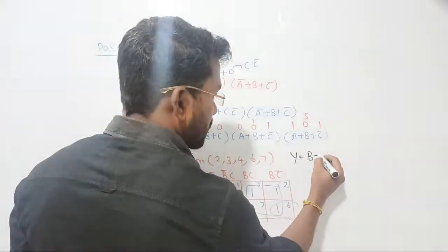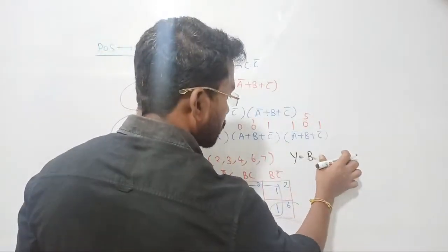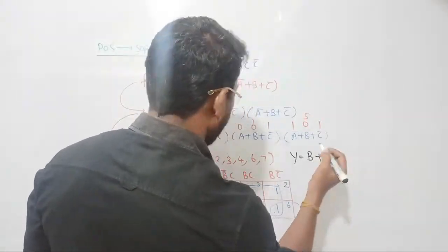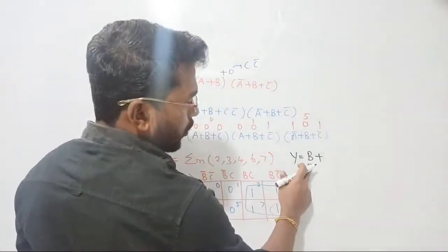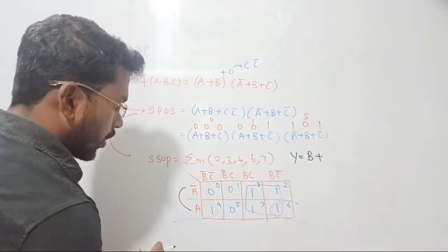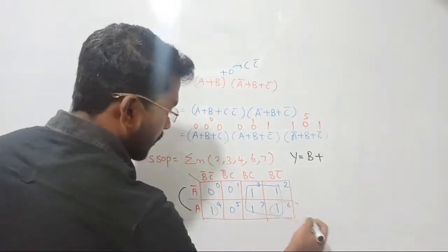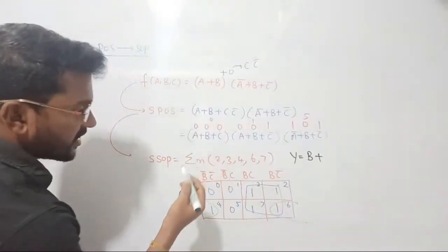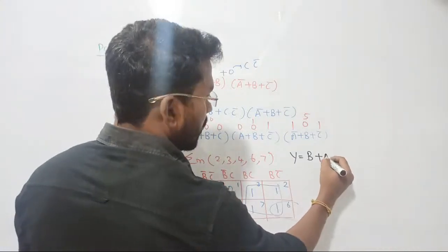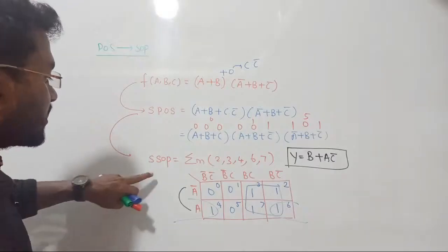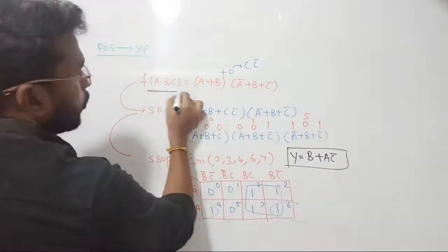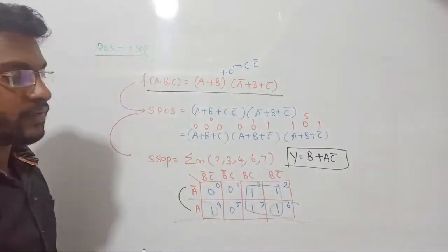So similarly, plus, sorry, not plus, yeah, plus only. We are writing what? Sum of product, right? Product is over, and then we have to perform OR operation in order to add the second variable. So if you add, here we are considering A. Now the common variable between these two is C bar, such that your answer is going to be A C bar. Clear? So that is the equivalent Boolean expression in standard SOP form for the given product of sum. Clear?